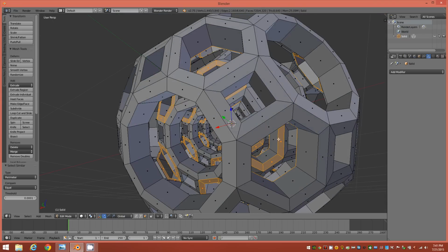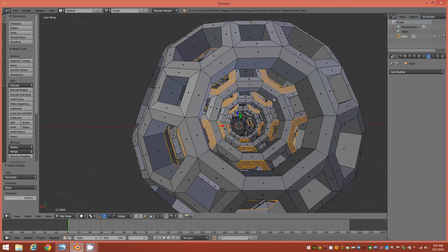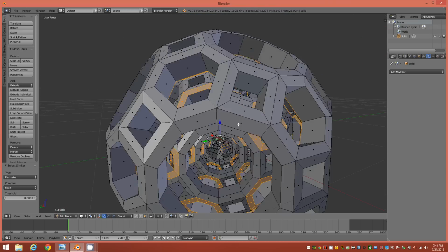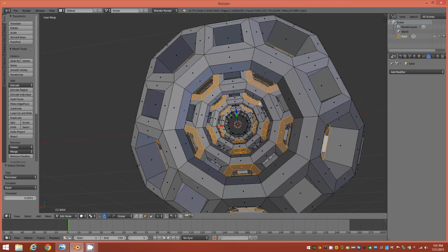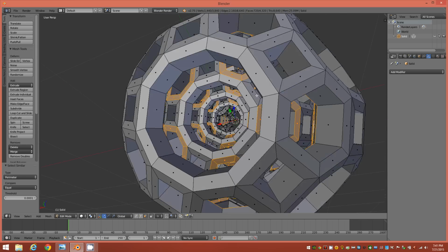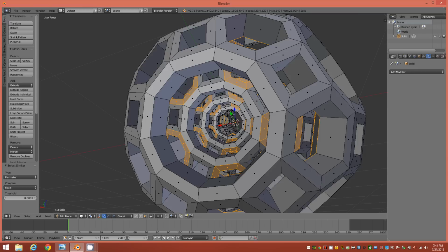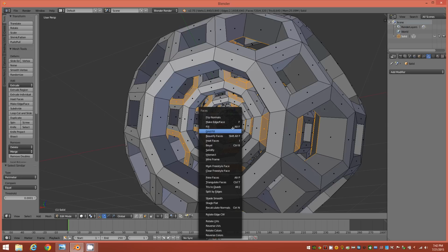We're going to need these face selections again later on, so we need a way to preserve them in case we lose them over the course of our workflow. There are several ways you can do that in Blender. One quick and easy way is to hold down Control and tap the F key to bring up your Faces menu.